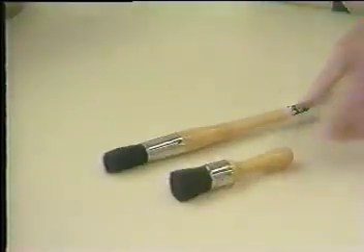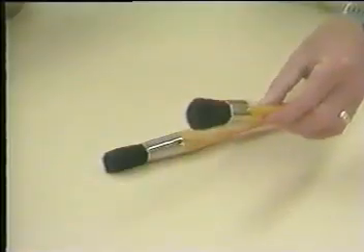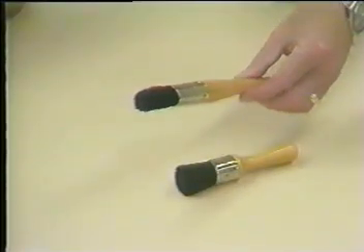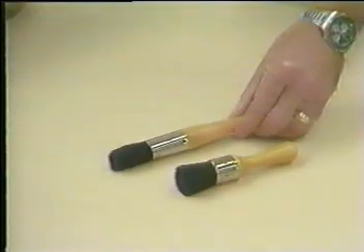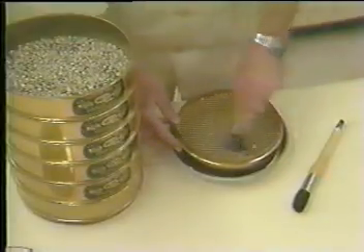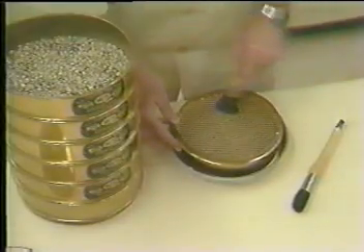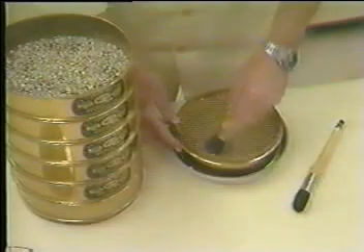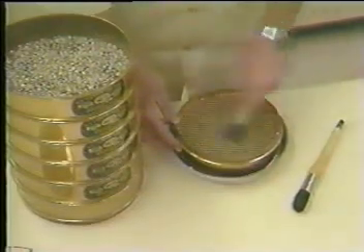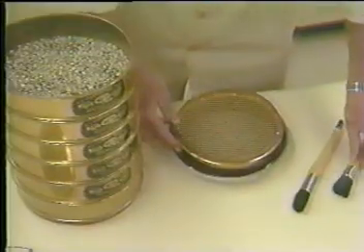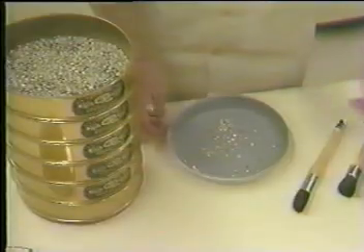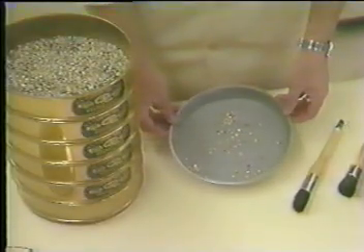Remove the particles from each sieve using a stiff bristle brush for sieves 50 mesh or larger, or a soft bristle brush for sieves 100 mesh or smaller. Take care not to damage the wire cloth by too much pressure or by scraping action. It is unnecessary to remove all particles lodged in the sieve after each use. To ensure that none of the particles being removed are lost, we have placed the sieve top down in a pan large enough to accommodate the sieve. Other methods may be used.